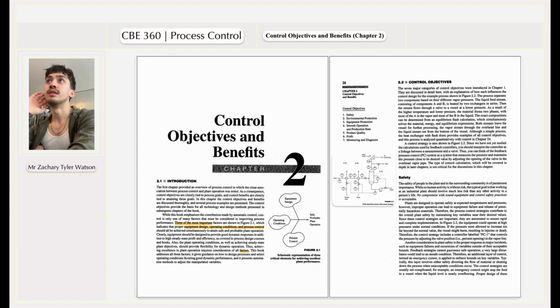In figure 2.2, the pressure is controlled by the element labeled PC. Normally, it maintains the pressure at or near its desired value. However, the control strategy relies on the proper operation of equipment like the pressure sensor and the valve. Suppose that the sensor stops providing a reliable measurement. The control strategy could improperly close the overhead valve.